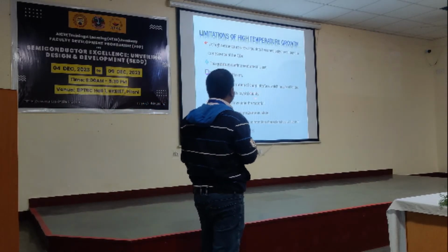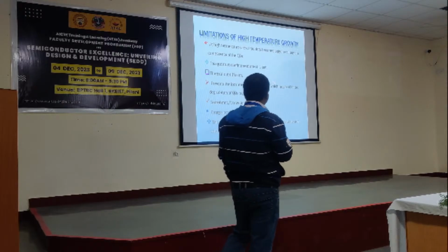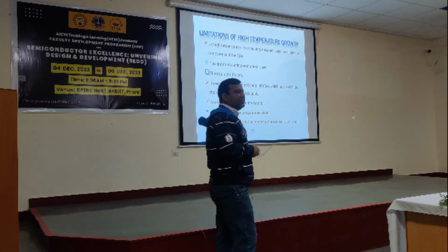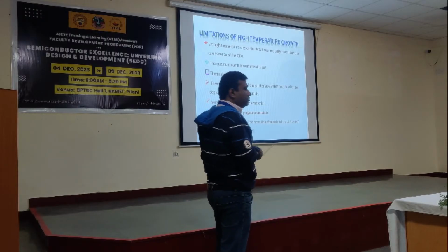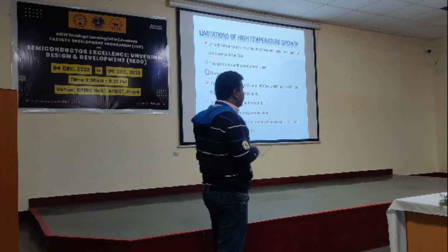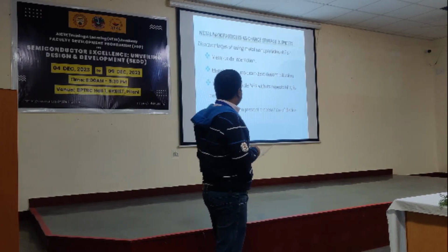It also prevents the formation of a sharp interface, which facilitates the degradation of the crystal quality. Sometimes it may even dope the material. Eventually charge loss takes place from the bigger quantum dots, so that greatly degrades device retention characteristics when you are fabricating non-volatile memory devices.